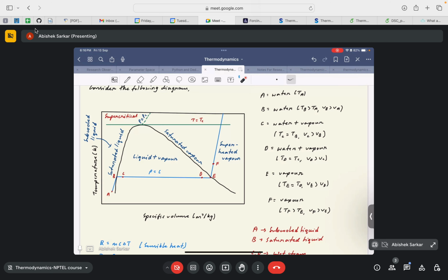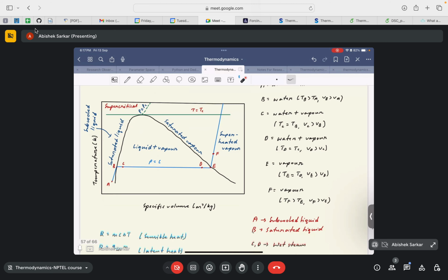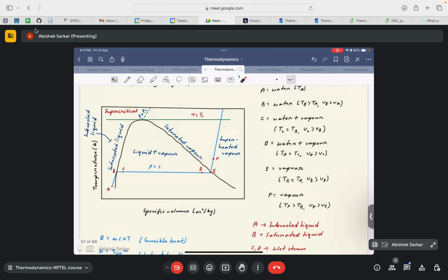So vapor is in a higher energetic state, so the energy from the heat applied is used to change the phase of the water from liquid to vapor, right? And this region or line denoted by B to E is specifically known as the phase change region, right? One important thing to note is that the pressure throughout this phase change process, at least in this given plot, remains constant. This pressure is known as the saturation pressure for this particular temperature. Say T is the temperature at which the phase change is occurring; this constant pressure, or isobar, is known as the saturation pressure corresponding to this temperature.